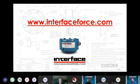The load cell pictured on the screen, actually, that connector typically wouldn't be great for moisture, in that the back shell of the mating connector isn't super well sealed. But some overmolded, other kinds of connectors can be great. So it's really important to talk about these things as we're specifying what load cell and what cable to use, other than finding out the hard way later.